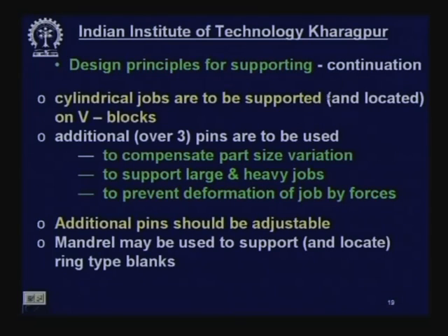Now, the design principles continuation. Cylindrical jobs are to be supported as usual on V blocks. Now, additional pins are to be used to compensate part size variation. If the part size varies widely, then additional pins will be required. To support large and heavy jobs, more than 3 supporting pins will be required. To prevent deformation of the job by heavy forces, more supporting pins will be required.